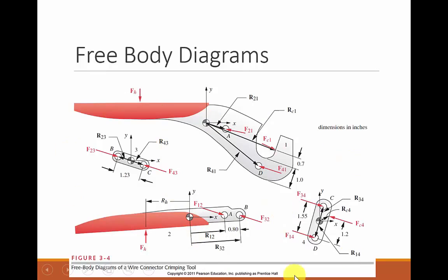This becomes just a geometry problem, a basic statics problem. Given this force right here, and assuming statics, so assuming that we're not moving at this point, we could calculate all of these forces. Once we have these forces, now we have enough information to calculate this force. Using this force and a relationship right here, now we can calculate this force. And using all of that information together, we now can calculate this force and finally back out what FH actually is. Okay, so there's a quick reminder about what free body diagrams are.